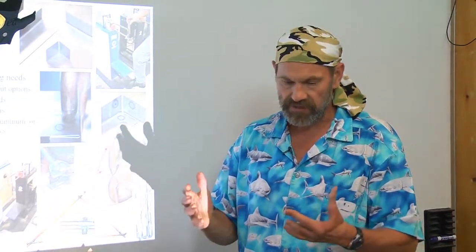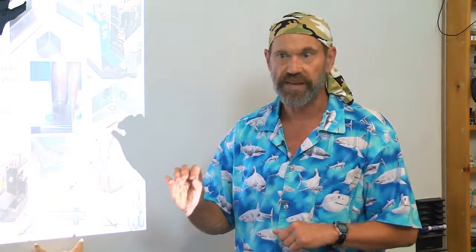Why is that? A lot of materials achieve their strength by heat treating. When you weld them, you raise them very hot, and then they're quenched by the air or the material around them, and you change the heat treat state of the material. So be very, very careful, if you're specifying a welded joint, about what that does to the strength.